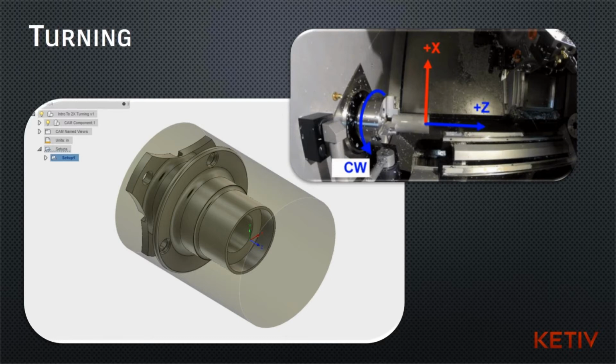Also notice that the part is going to be rotating clockwise. If you look at the part, you may be thinking, well, that's not rotating clockwise, that looks like it's going counterclockwise. But this is rotating based off of the machine's view. Mark Terryberry, a Haas applications engineer, does some pretty good videos on YouTube, and he has a pretty good analogy for describing the rotation.